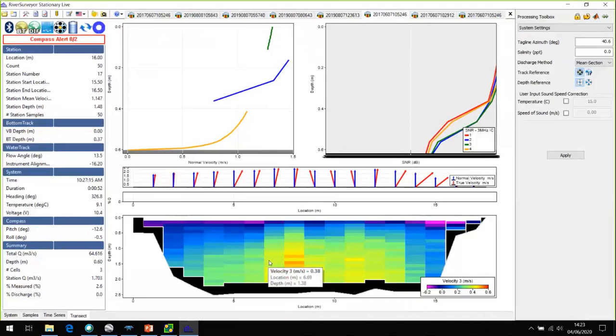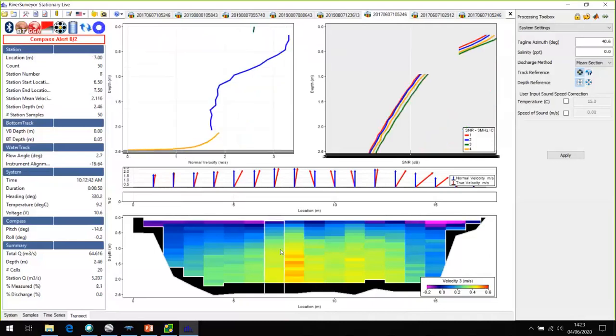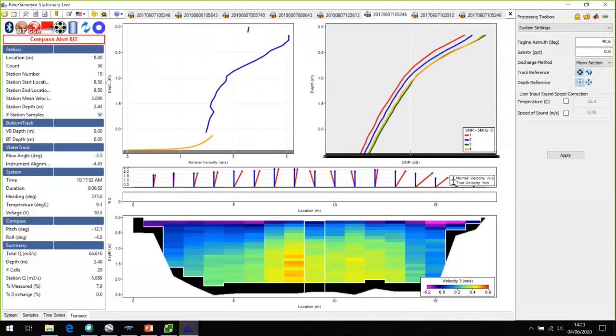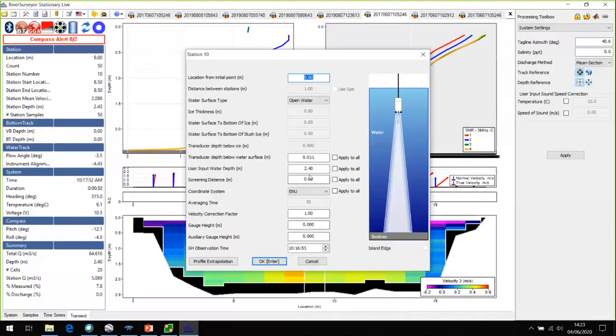Yeah, so first of all, at this site you'll notice on nearly every station, this sort of sunset symbol up here on the top left, I call it sunset, it's nice. It means that the ADCP is not measuring the depth. So all these depths are manual. And the guy who got this gauge in, it wasn't me unfortunately, but it's my station. So to get the ADCP to work, if it isn't going to measure the depth itself, which it didn't, put in a manual depth and then it will measure.